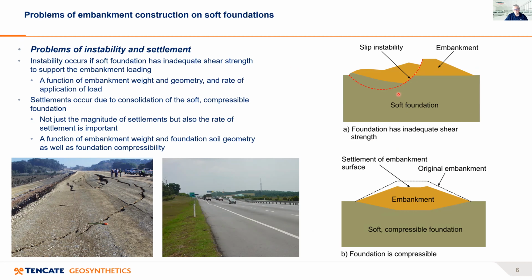This instability is really a function of the embankment weight and the geometry of the embankment. And it's also a function of the rate of application of the load. For example, if you apply the embankment load too quickly, you can shear the soft foundation. Whereas if you apply the load a lot more slowly, you won't shear the soft foundation.